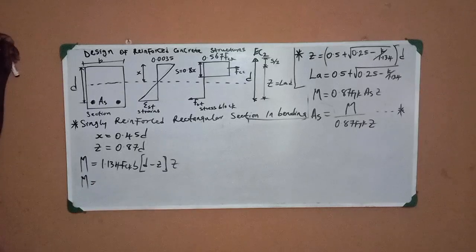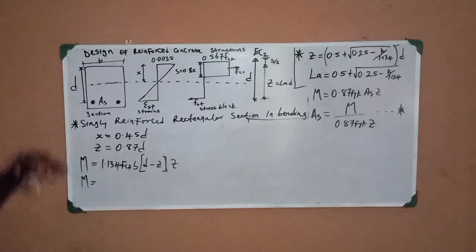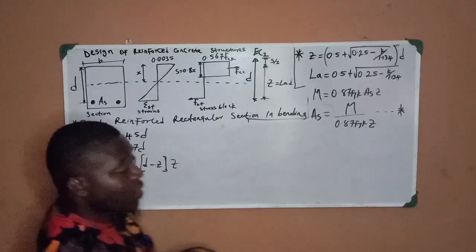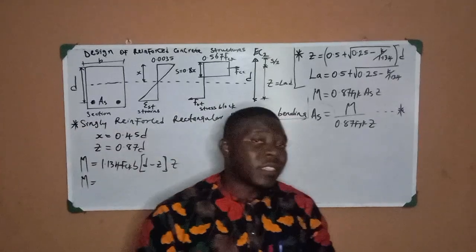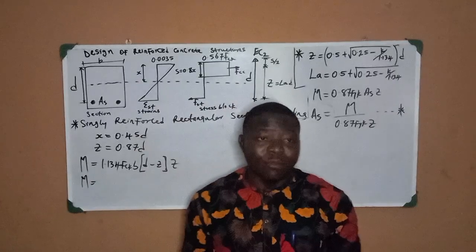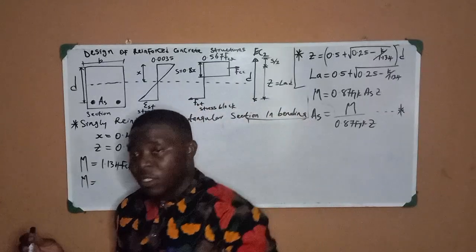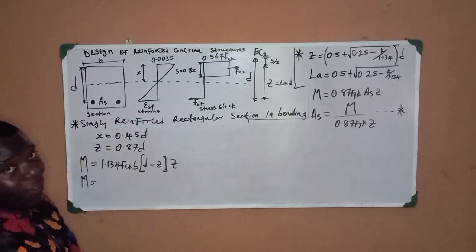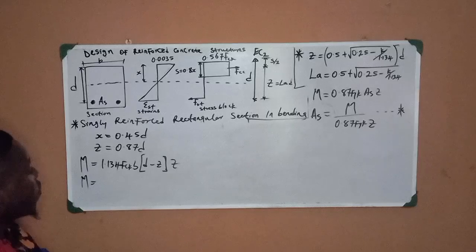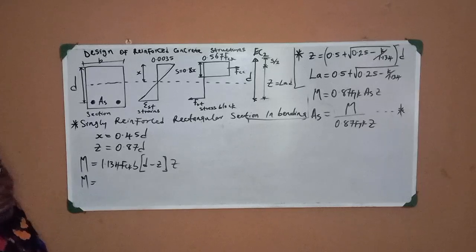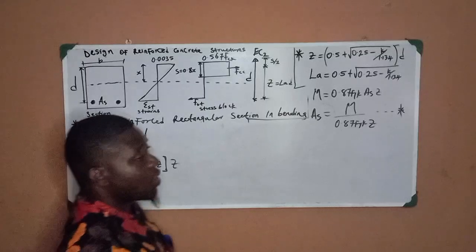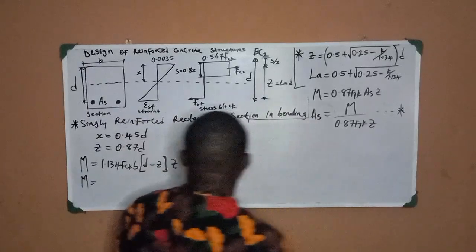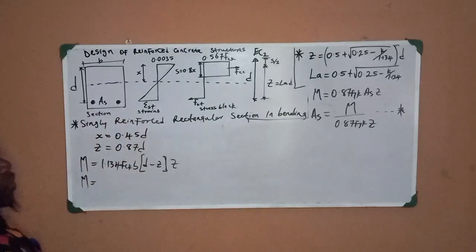That's the maximum moment that you have to use to compare, because during your calculation, the applied moment and the moment of resistance must be equal for you to provide only reinforcement in the tension zone. At a point whereby the applied moment is greater than the ultimate moment of resistance, in that way there will be a need to provide reinforcement at the compression.